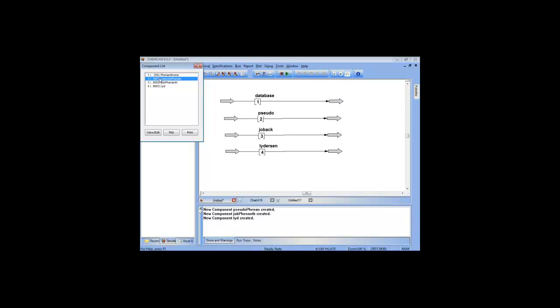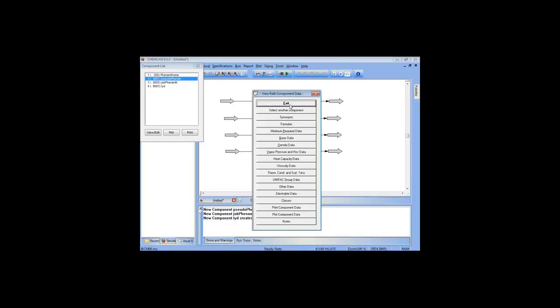If you started using CHEMCAD with CHEMCAD 6, don't worry about this number. If you're watching this and you used CHEMCAD 5 or CHEMCAD 4, you might be thinking that you've found the secret way to use the 8,000 numbers. No, you haven't. Please don't assume that pseudophenanthrene is always 8001. The first user chemical is called 8001 in this simulation. So if you're a new user of CHEMCAD starting with version 6 or later, don't worry about anything I've said about the 8000 number. If you're a legacy customer, thank you, and give us a call to talk about that number before you try and do anything creative.